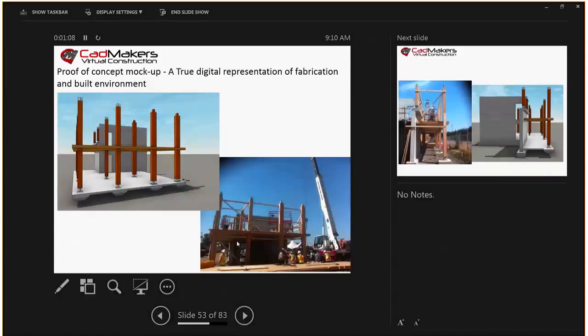I'm just going to fly through this. This mock-up was the first time we were able to test whether we were really going to be able to build the structure as fast as we hope, because there's a premium on the materials. Mass timber is a little more expensive than concrete for an 18-story building, but if we can make it up on speed, overall net, it's a strong pro forma for the owner.